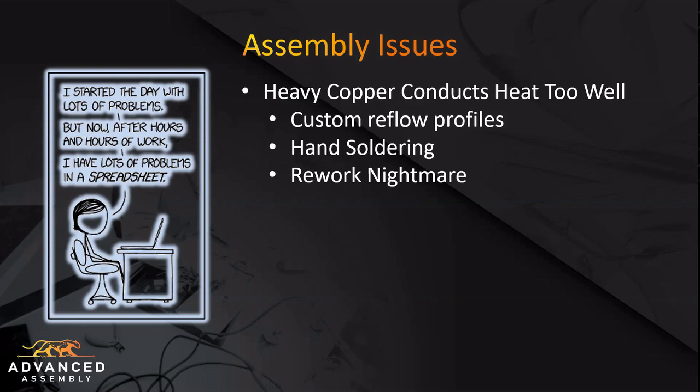Wrong. So now where we're at, we're really introducing more heat and really heating up the boards. And it's really at this point possible to cause the epoxy or fiberglass to decompose prematurely, like we talked about. And this is where vias can also experience some types of cracking and a host of other problems.